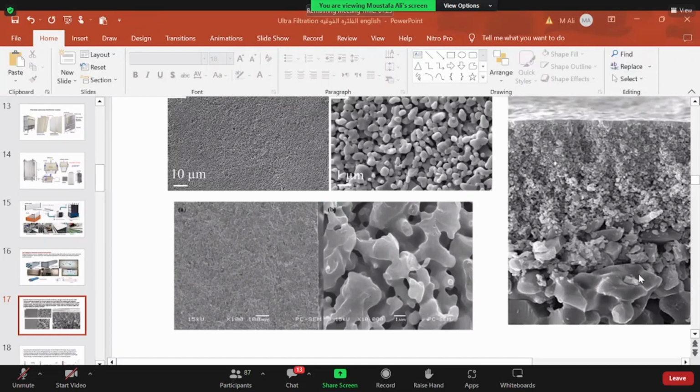We have this coarse particle layer, the main frame, which we call the flat sheet. We just submerge it inside the mud solution, the fine silicon carbide particle solution. Then we take it out, so a film layer is formed on the surface. This film layer is kept to dry, and after that it goes to the furnace to be fired again, as the main frame was first formed.